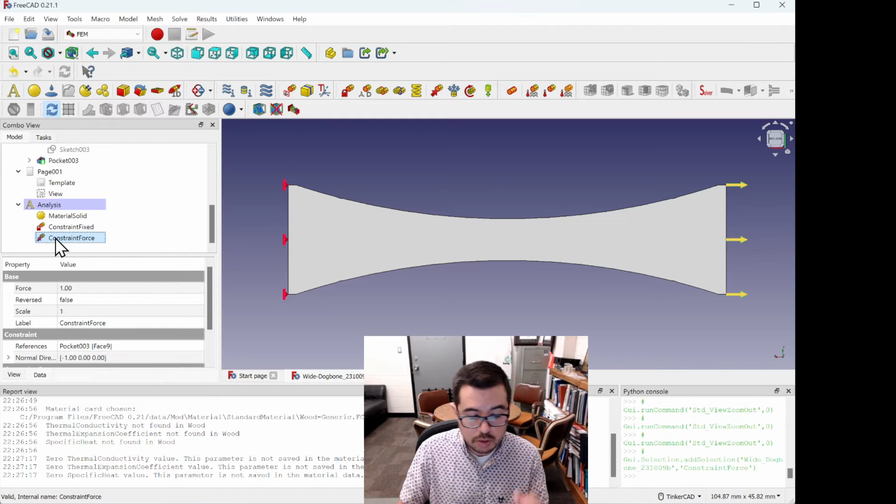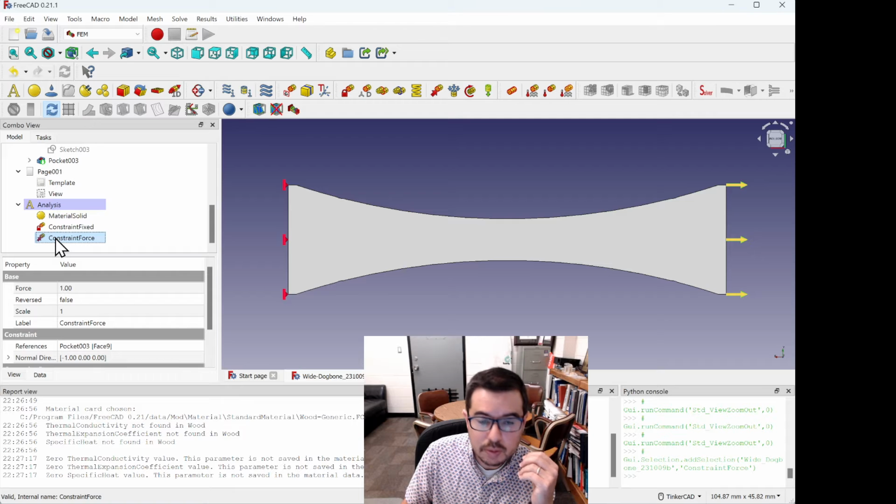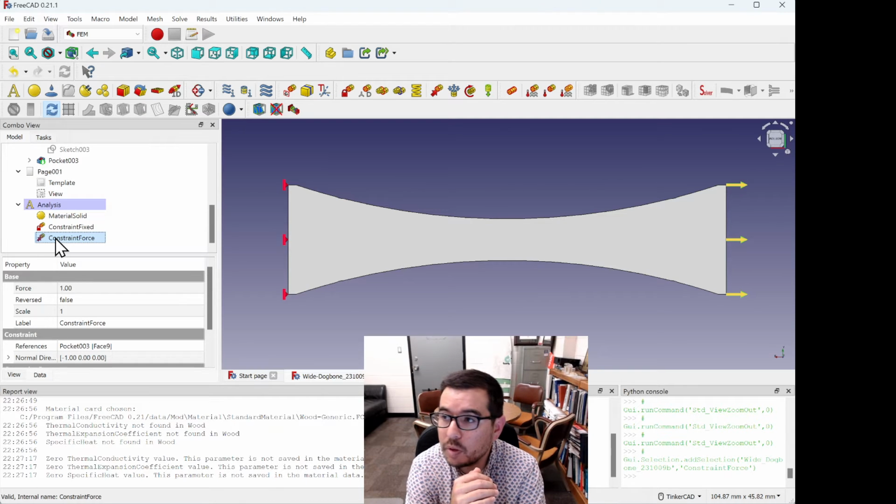What I really should do, though, is specify the force that I thought my material was going to break at. It's been a while, but my breaking force was 1.5, my safety factor, times my design force. So I had a design force of 50 newtons and a safety factor of 1.5, which means that my breaking force was 75 newtons.